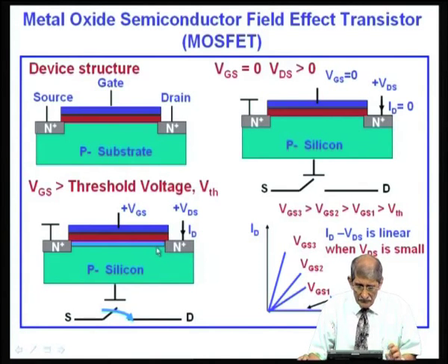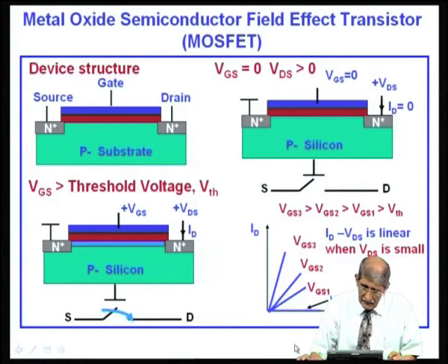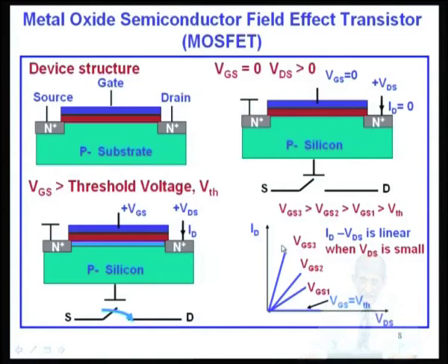Okay. Now, if I keep increasing, the current goes in that direction, and the voltage drop from here to here increases. Initially, when this voltage drop was negligible, throughout a voltage of 1 volt was available between the gate and the channel to create the charge.